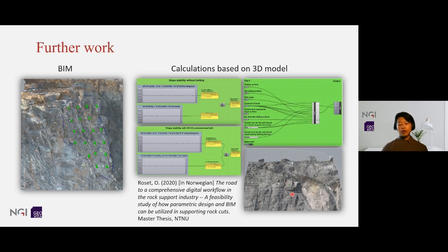This will help engineers to easily produce designs, and ensure that the design will comply with the standards. The next procedure is to enhance the workflow, the information flow between design and BIM, and make it easier for production. We are developing a procedure on how to use Rhino Grasshopper to export design to BIM, where each of the objects will carry metadata that tell you, for example, the bolt diameter, the bolt length, and also the material.